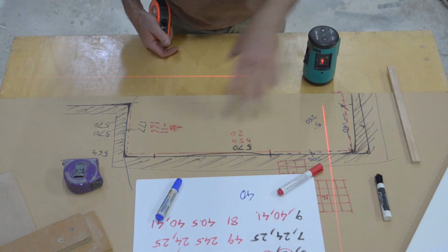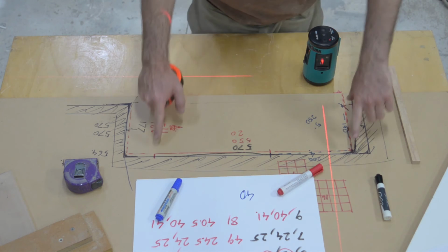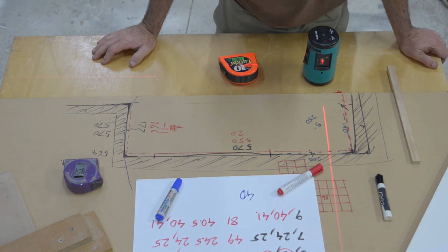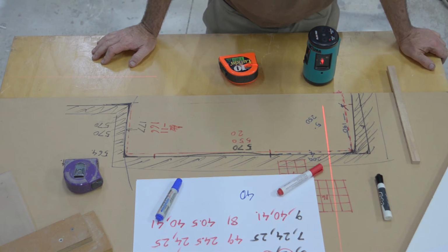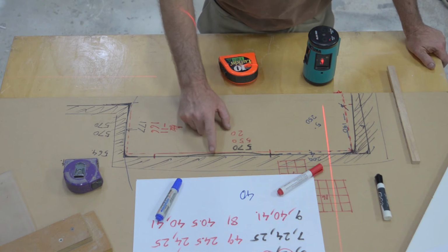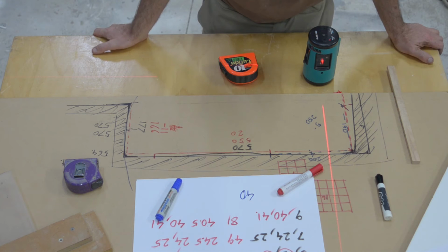If you don't have these tools, you can use this method with the various triangles and a tape measure and your tool to mark with to establish a square, or you can simply build in ample tolerance, like guess that 10 millimetres is the gap, and so we're going to allow, say, 20 just to make sure it's safe. So they're the three real options. Either measure it well, so you know your numbers precisely, but if you've got the tolerance, just use the tolerance and create tolerance to make life easier.